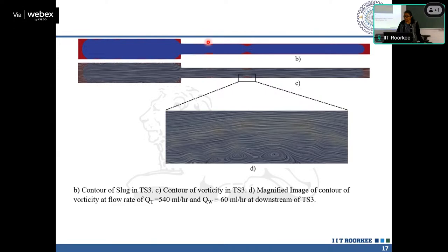So this disturbance wave, which results from the sudden abrupt change in the flow path, is actually enhancing the mass transfer in the downstream. Otherwise it is the 2 mm, isn't it? And the 2 mm straight tube gives us the lowest efficiency. It is due to this phenomenon that the mass transfer efficiency of such geometries is higher.